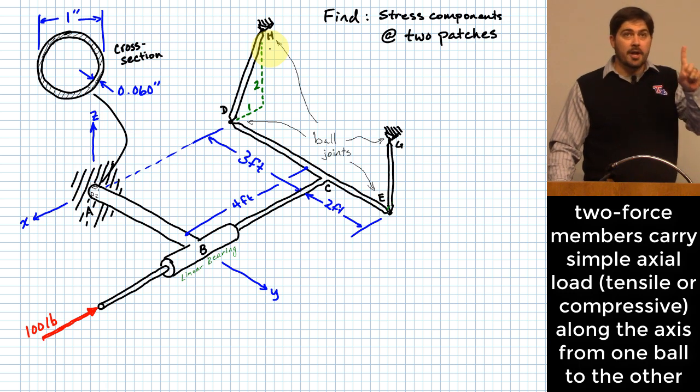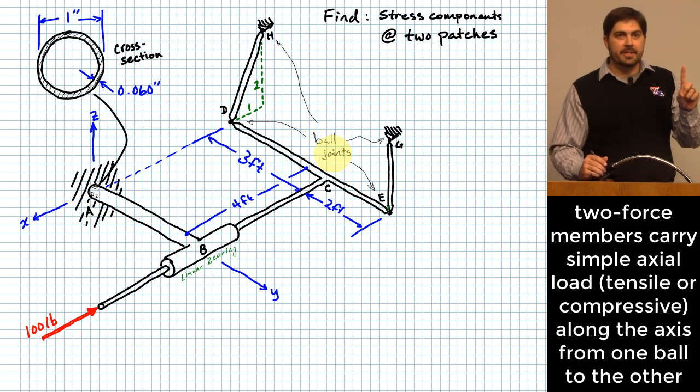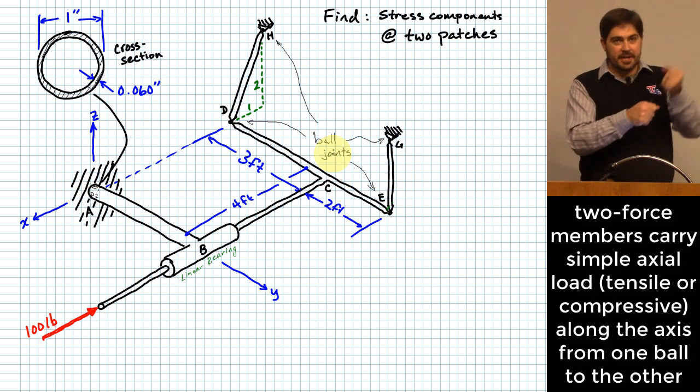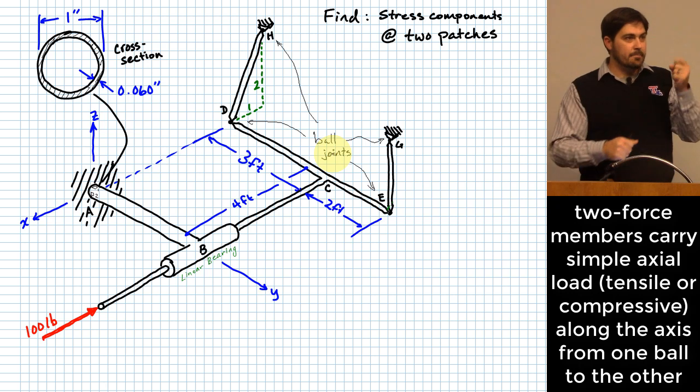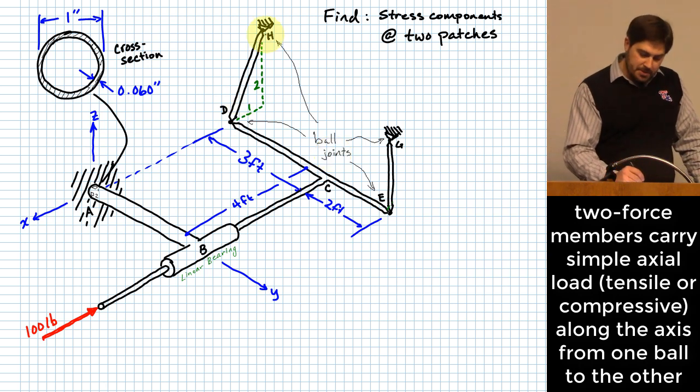Right, there's one unknown associated with the force carried in either one of those members. You can purely boil it down to a certain amount of either tension force or compressive force, but that's just one unknown, because you already know the line of action along which the force will be applied for those two members, DH and EG.